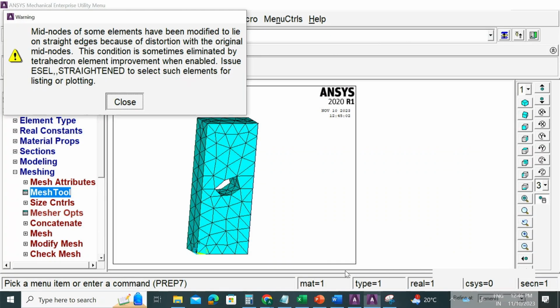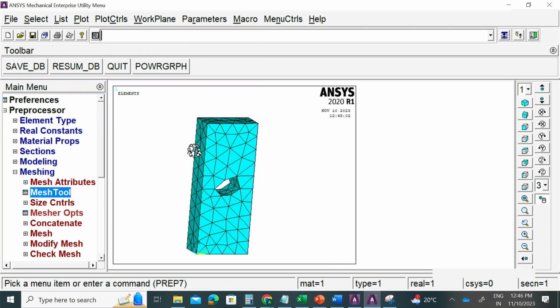The next thing which I'm going to do in order to start my mesh convergence study, so we are going to learn the sizing control and the mesh convergence study together. That way we are saving time here. So this is the first mesh. I'm going to go ahead and apply a load and a boundary condition, or a constraint, here and fix that constraint and not change that. I'm going to only keep on changing the mesh and look at the results. Okay, so that's the goal.